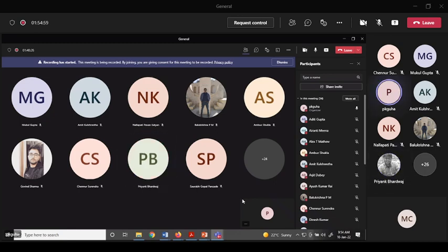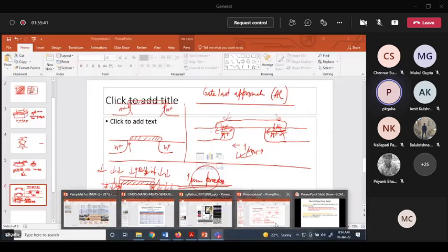Sir, when we say that we want a good gate control, is it the same as saying we want high capacitance? Good question. No, high capacitance is probably a loose term. But the thing is, in scaling down, your capacitance is going to reduce, as you said, because there is epsilon A by Tox, right? If you scale, you have to reduce A, that is W and L, so there is alpha square. Probably you are pointing out that.